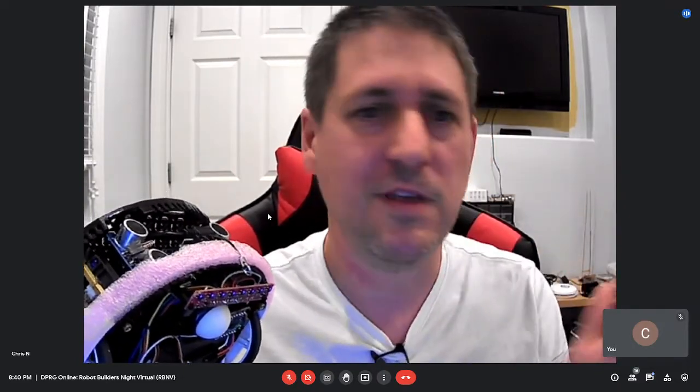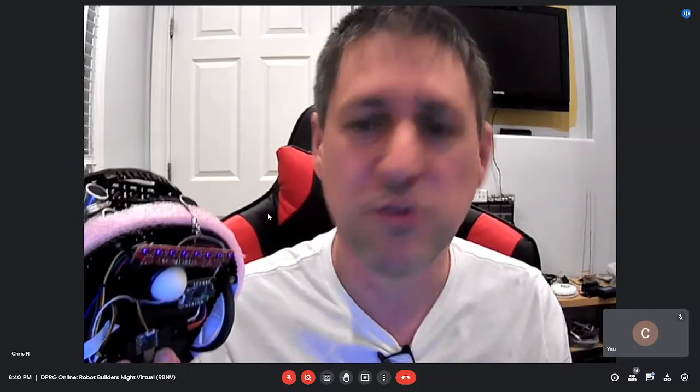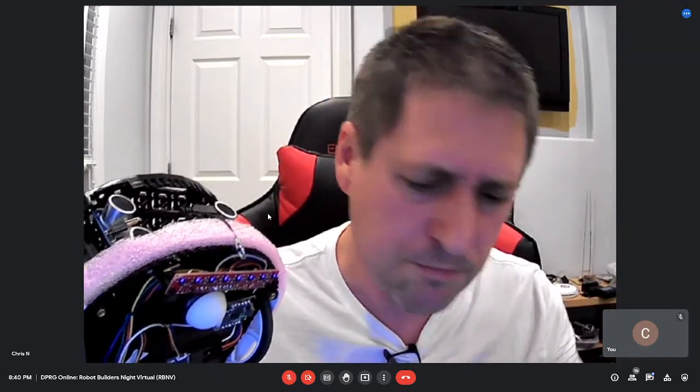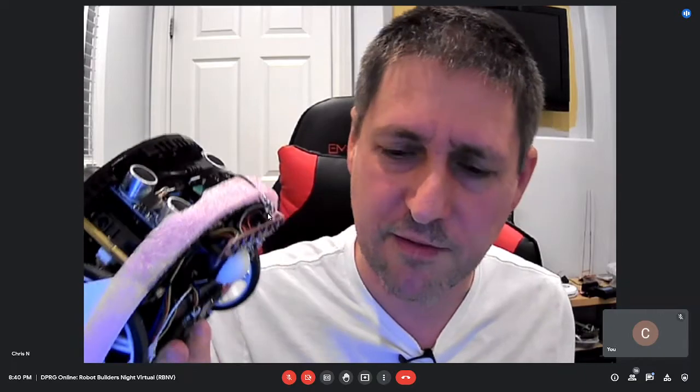Both the calculated odometry, meaning X, Y, and theta, is getting published. I'm also publishing the raw encoder clicks, just in case I ever want to do something different with them. Right now I'm not using them. I'm just using the X, Y, and theta directly, but the raw encoder clicks are there if I ever want to use those directly.